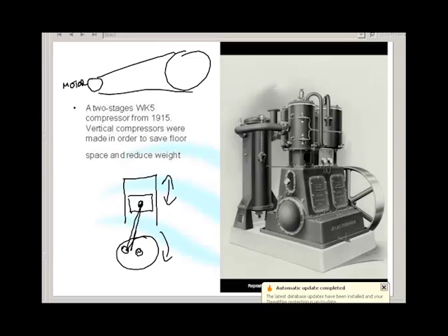Yep, that's the thing. If you start this thing up under load, all that's going to happen is the motor will start up, there'll be an awful lot of screeching, the compressor house will fill with smoke, and you'll melt the belts. You cannot start this thing under load. What this has is these things here, and these things here, they're called unloaders, or decompressors.